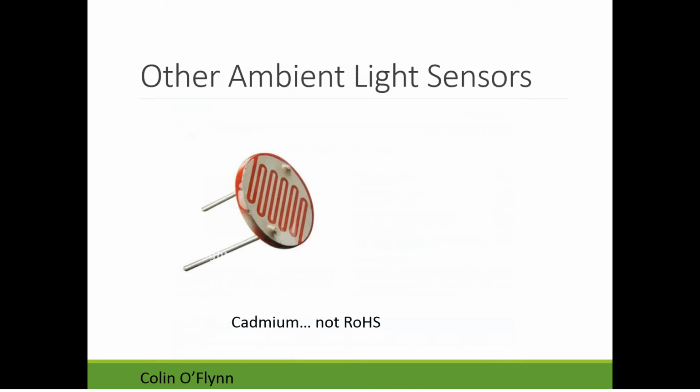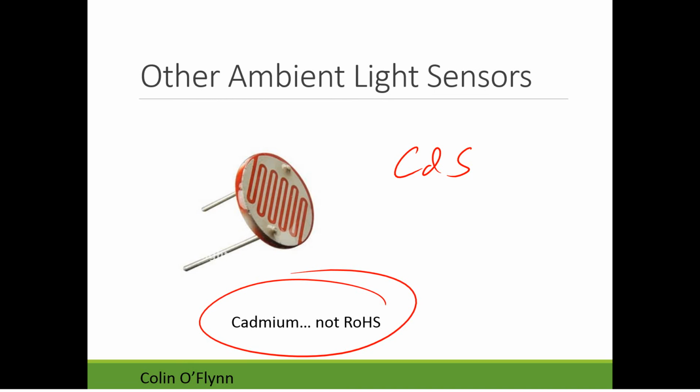It replaces what you probably have used or are more used to, which is this type here, CDS. These light sensors you saw in everything, like outdoor motion sensitive lights that turn off during the day, always had these little light sensors. They're really cheap. They're not as popular anymore because the cadmium in them is banned under the European Restriction of Hazardous Substances Directive. Because of this, you more or less can't use them in Europe for a lot of applications, and people are now using alternatives.